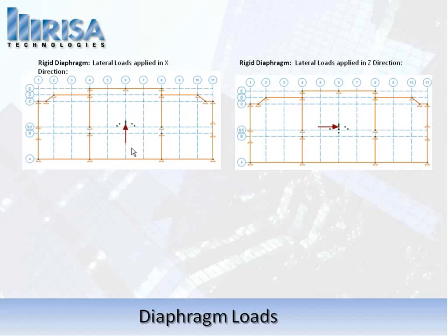Okay, for a flexible diaphragm, there's actually an entity of a rigid diaphragm there. Internally, the way we talk about a rigid diaphragm is sort of just rigid links that tie everything together on that level. Then as you apply forces on that level in the lateral direction, everything distributes out to those walls. So that's a rigid diaphragm.